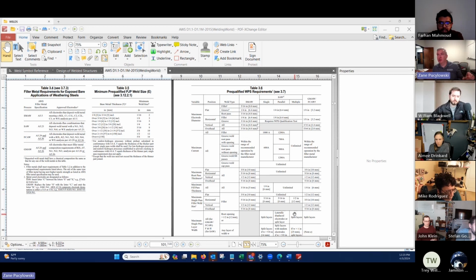I'm constantly looking at this when we're trying to figure out welds because I'd like to do it all in one pass if I can. Otherwise, I put in a lot of heat. And the other thing is when I come in for the second pass, I actually have to grind out a portion of the last pass to make sure I have good, sound weld material, and then I can make my next pass. Even for the gas one?